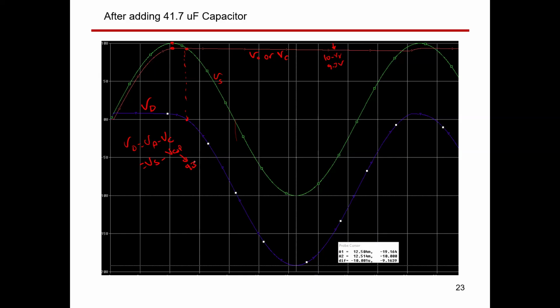So in this case, guys, if the supply volt became minus 10, which is minus V maximum, the capacitor volt, can you see the value here? It's going to be minus 10, minus 9.3, so minus 19.3 volt. It was different in case of the circuit without capacitor.